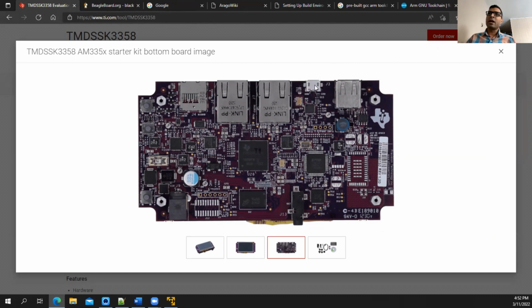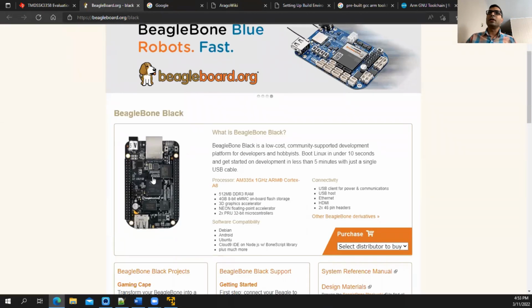They provided us a USB micro, and it's connected to the FTDI chip and then connected to the UART0. So in this case, we have access to the debug port easily by the USB cable. And we have a power input. In my board, I have a Wi-Fi module connected in here, but in this picture, it doesn't have. The same chip is used on the BeagleBone as well.